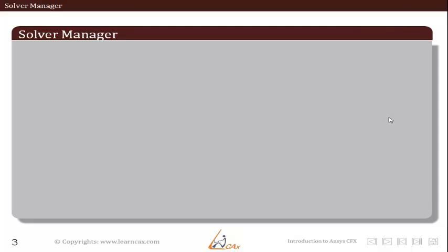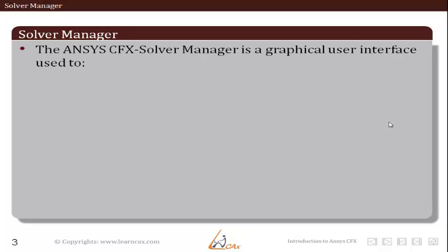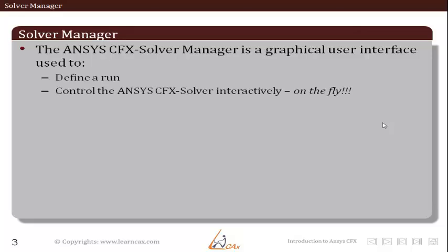So what is CFX Solver Manager? Solver Manager is the graphical user interface of ANSYS software which is used to carry out simulation data calculations. It is used to define a run. It is also used to control the ANSYS CFX solver interactively on the fly. This means when the CFD data calculations are going on, we can change the settings and change our run when the solution is running, and the solution or CFD calculations get updated simultaneously on the fly.